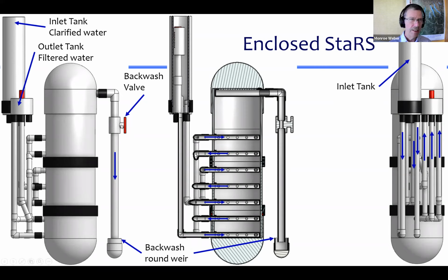There's no longer an air release valve that is used to trigger backwash. Here we just use a standard valve, and that's partly because these are now much smaller valves and they're not so expensive, and so it's not worth going to the air lock system.